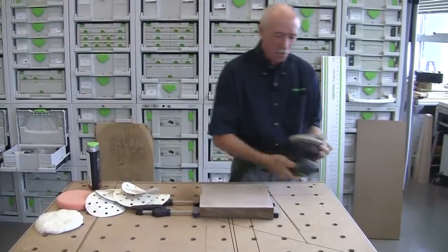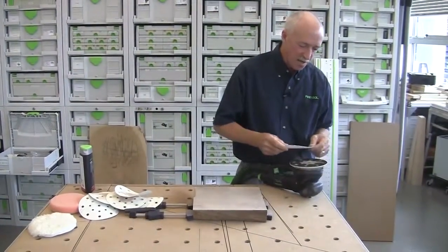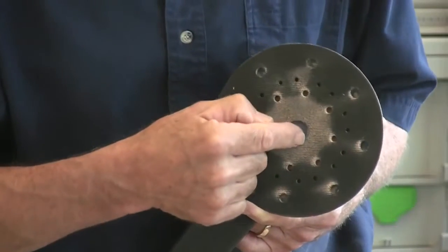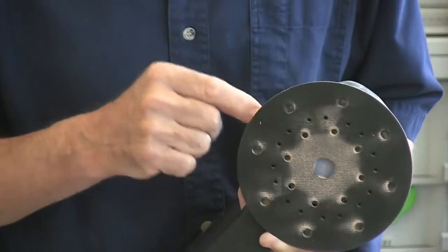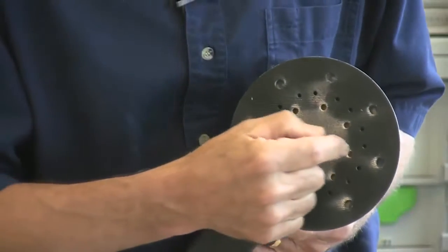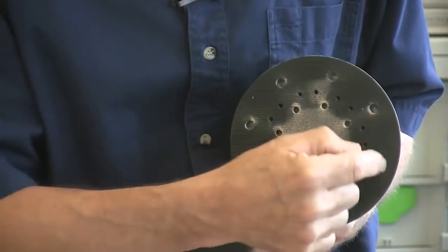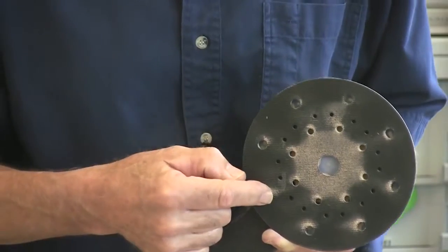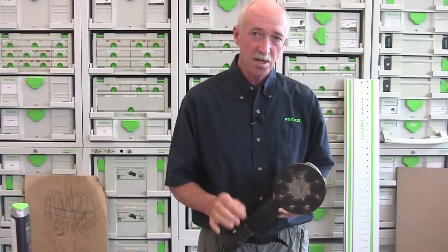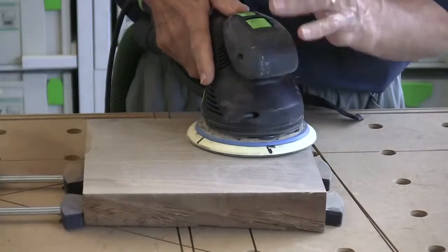Okay, this is our last grit, and then we're going to go to the next phase. And by the way, look at the pad. Air actually comes out of the center hole because it's pulled in through the holes of the pad. There's better airflow. But it's extracted through your center holes, and anything that's left is picked up by the outside holes, but it never gets to the outside of the sander. So if you keep the pad flat on the surface, you'll virtually have no dust. Let's finish our last grit.